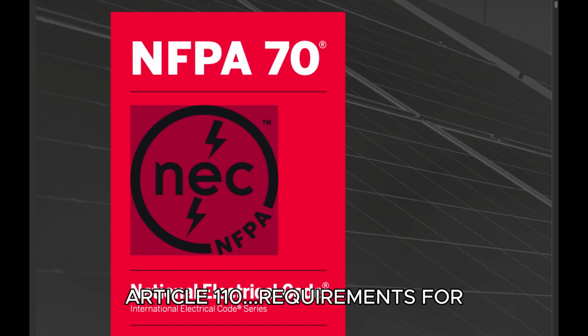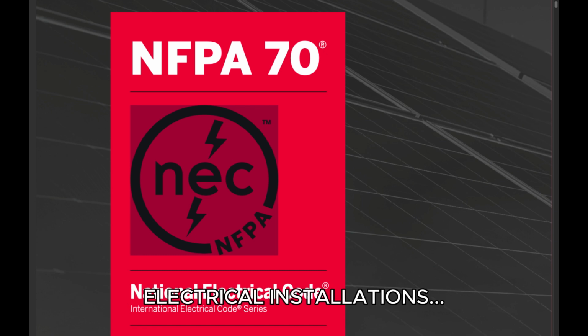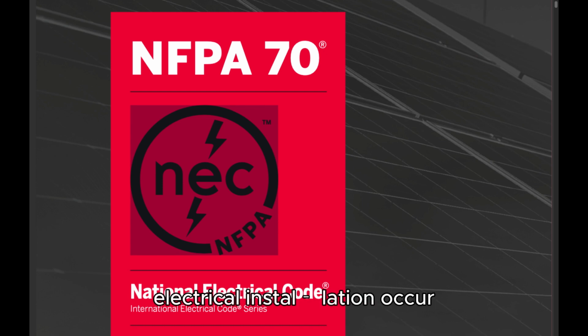Article 110, Requirements for Electrical Installations. Part 2b, Modifications. When modifications to the electrical installation occur that affect the maximum available fault current of the service, the maximum available fault current shall be verified or recalculated as necessary to ensure the service equipment ratings are sufficient for the maximum available fault current at the line terminals of the equipment. The required field marking(s) in 110.24 shall be adjusted to reflect the new level of maximum available fault current.